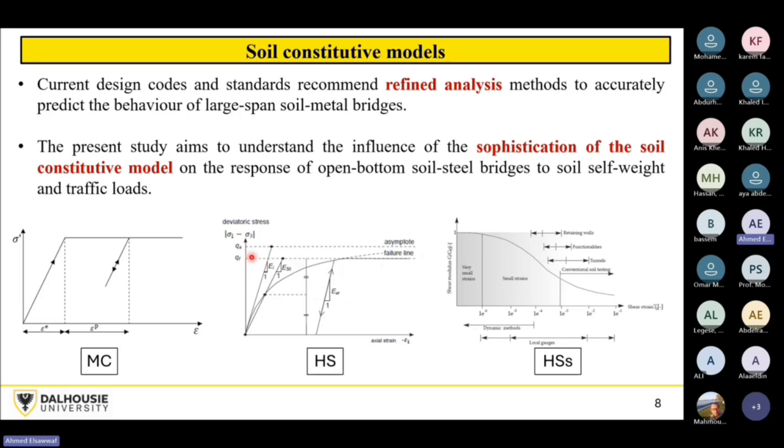In the hardening soil model, we have an advanced model, with a nonlinear stress-strain curve and 3 types of stiffness moduli defined and assigned to the soil, including E50, E unloading-reloading, and E oedometer. And if you remember 2 or 3 slides ago, I told you about the cut and cover technique. Here the E unloading-reloading value will play a major role in controlling the deformations, which we don't have in the Mohr-Coulomb model.